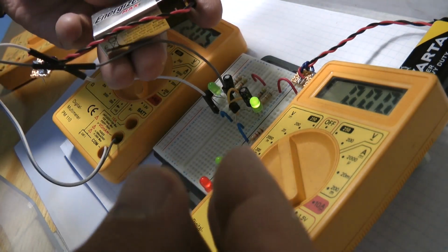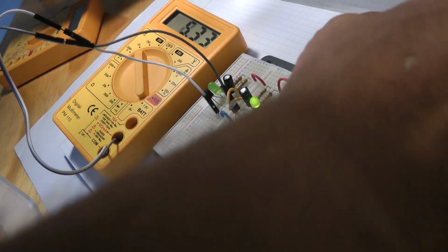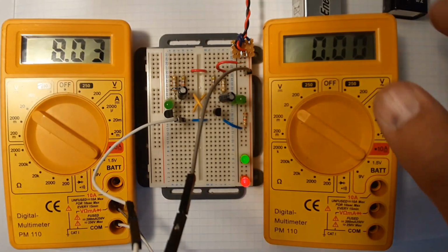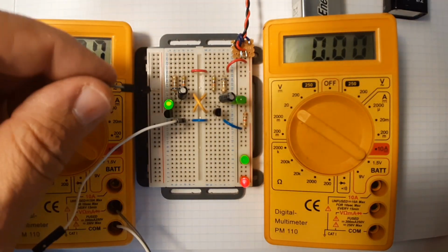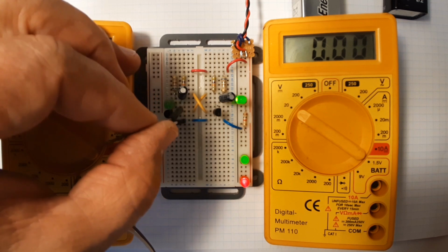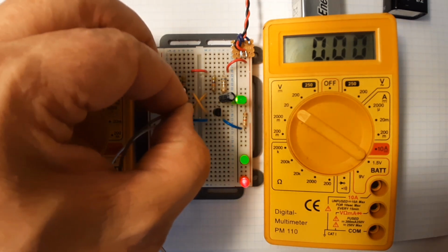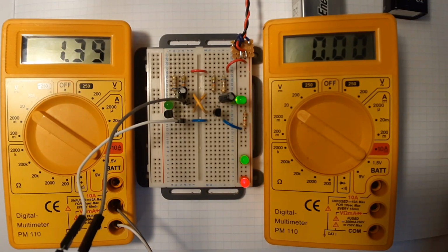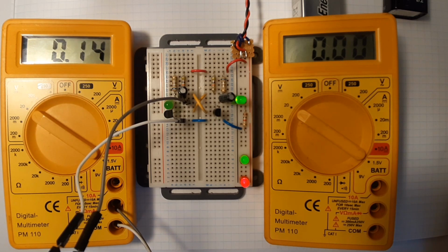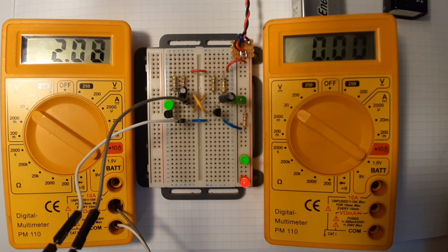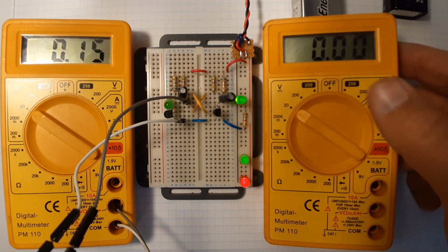I've got this battery which might have more juice in it than this yellow battery. This 9 volt battery's got 8 volts. So let's put this lead back to test point collector of transistor 1. And you can see it's fluctuating between 6.2 volts going down almost to 0. So if we had a 9 volt battery that was brand new, we'd probably be seeing a slightly higher voltage at that point. But now we've got this other meter here which is currently not doing much.